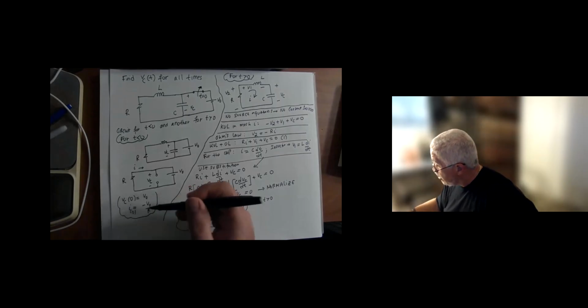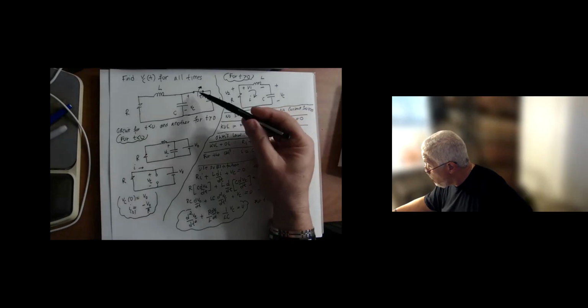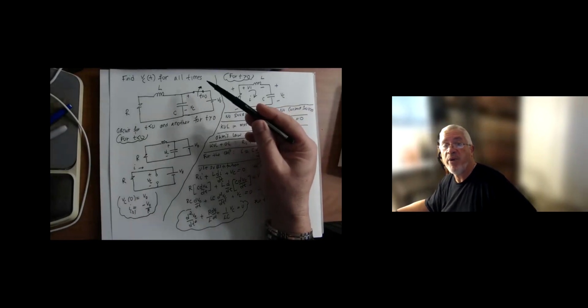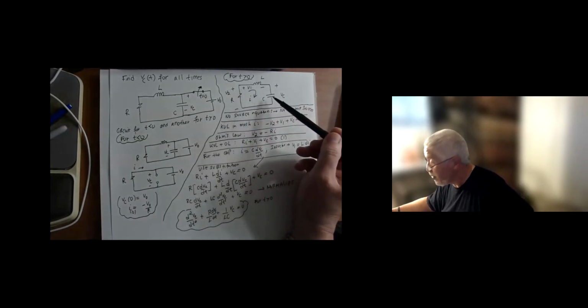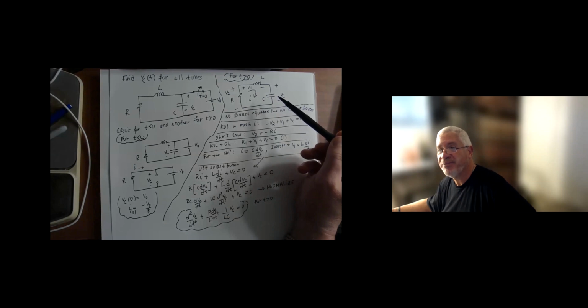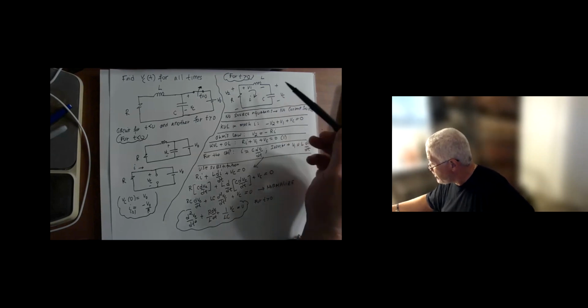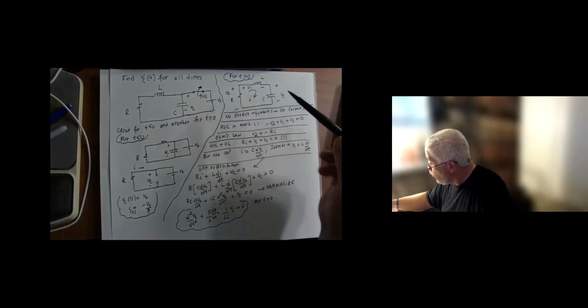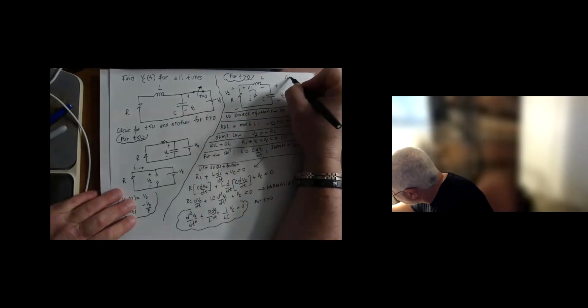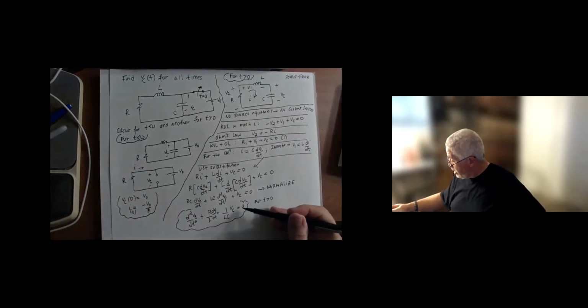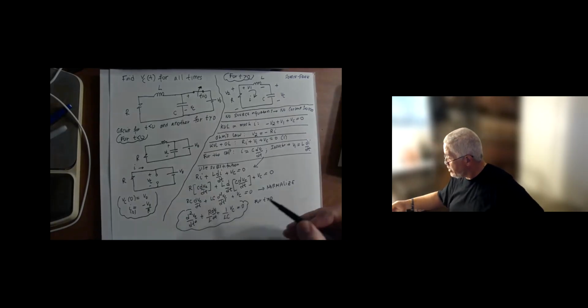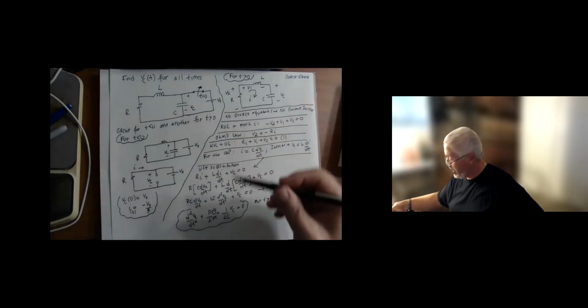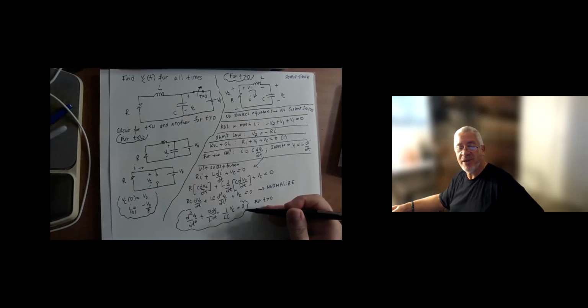So we did that. For t greater than 0, though, the switch changing, opening up, brings back the inductor and the capacitor because that created a change. All right. So now, obviously, once the switch opens, it disconnects the battery from the capacitor. So we are clearly looking at a source-free circuit, or zero input. Okay. So this is going to give us, obviously, a homogeneous differential equation because there is no source in that circuit. So you can expect the right-hand side to be 0, as we noted here.